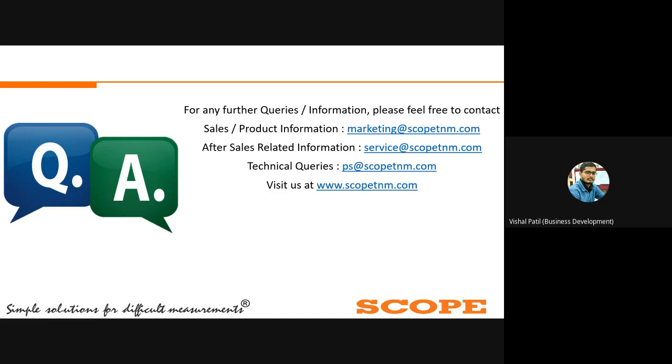Then there is another question from Mr. Santosh Kumar. In the water discharge test, what should be the water and salt ratio? Sir, in the water discharge test, you need to adjust that ratio at the time of discharge. First you need to put the positive and negative rods in the solution of water and salt, and you have to change the concentration of water and salt by monitoring the discharge current.